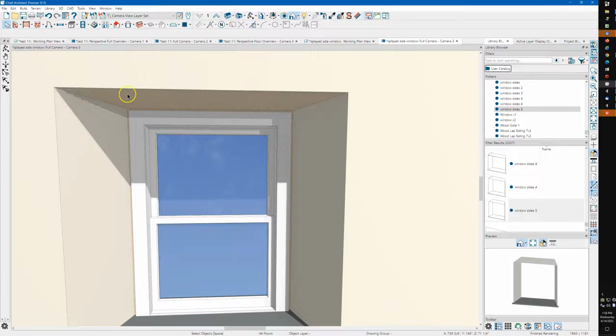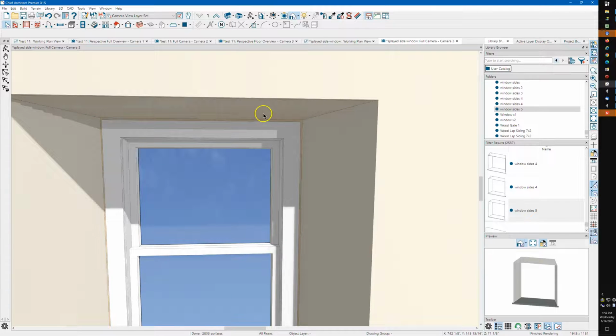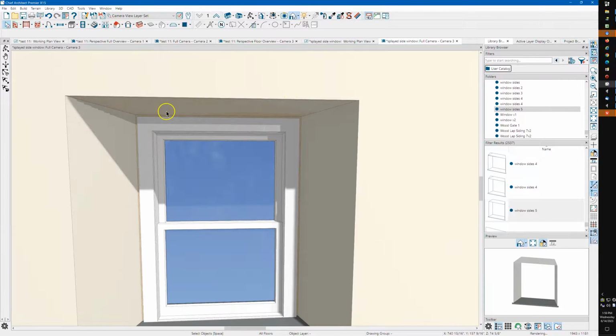So for this top piece, I guess I would not use a face. I would use a solid, and I'd make it maybe a 1/16 of an inch thick. The problem if you make it very thick, you'll see the edge of it up here, and you could fix that by exploding it and then being able to paint this edge across here the drywall color.